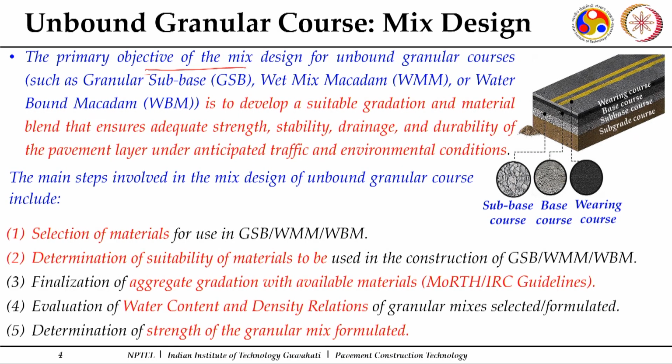So, here it says the primary objective of the mix design of the unbound granular courses such as granular sub-base course, wet mix macadam or water-bound macadam. These are three examples of unbound granular courses. What is done here is that the approach of mix design is to develop a suitable gradation and material blend. Now, the gradation, in most of the cases you will have already predefined gradations based on numerous field exercises and research which are usable for different courses depending upon the layer thickness and the aggregate size available.